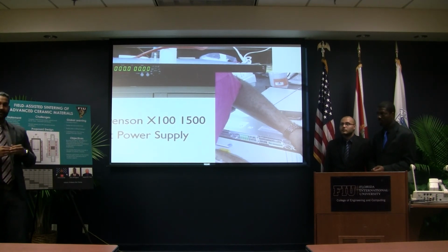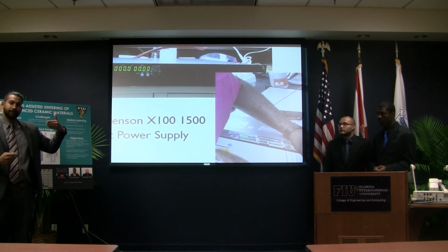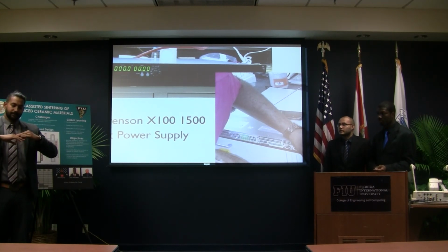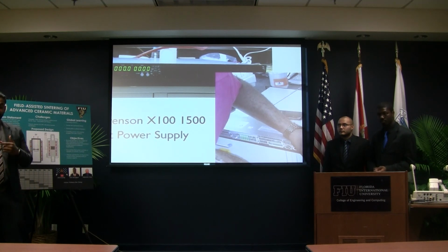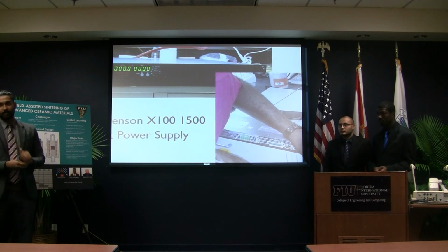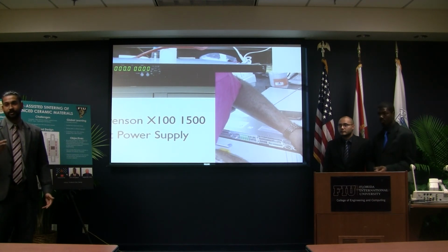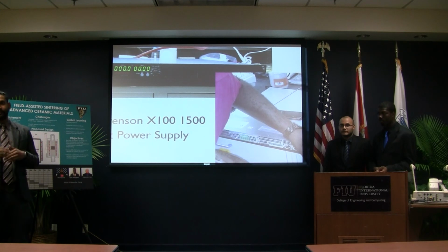So the new design is basically, we have platinum wire running through a ceramic tube that comes down and is glued with ceramic bond onto the aluminum oxide plating. And then just the end of the wire is sticking up on both sides, positive and negative, real close together. But I mean, that gap is really critical. Yeah, there's a gap, it's already glued and everything, we have one built. That way we can place a sample right on top of it, and then using silver conductive paste, hopefully get it to attach more securely onto those electrodes without falling off in any way, keeping the gap secured.